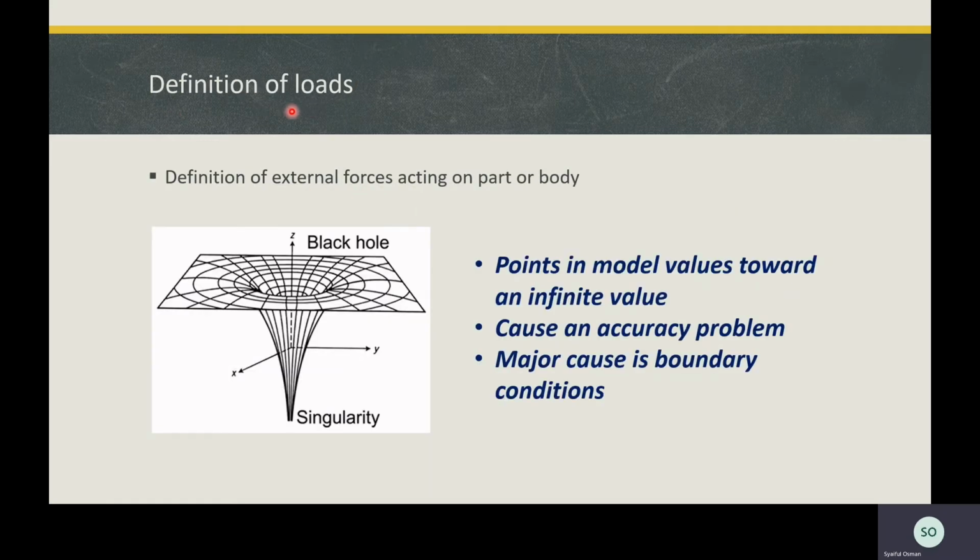The next step is the definition of loading. This step is about the definition of external forces acting on the part, or the body force by the weight of the component. In this step, we have to be careful about the force definition type in order to avoid encountering problems such as a singularity.